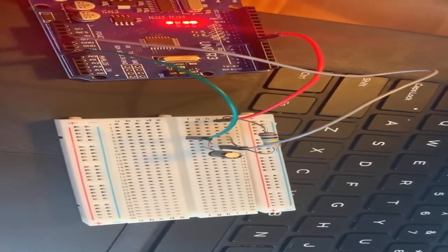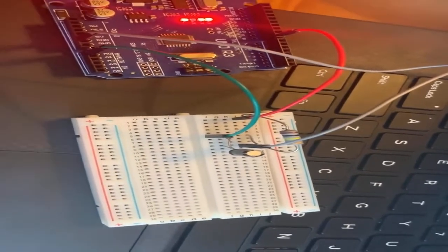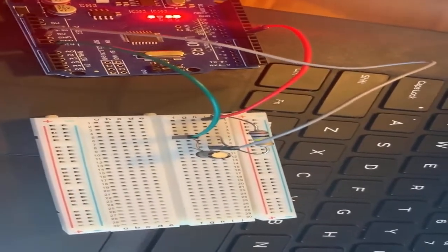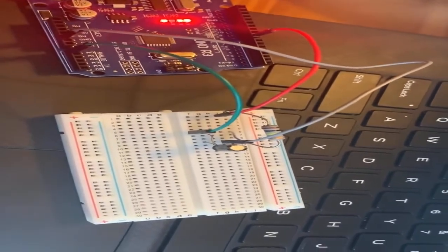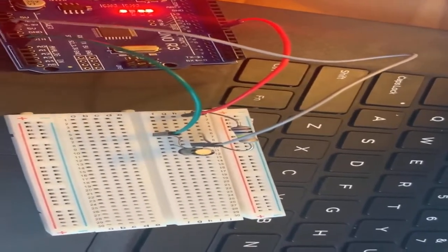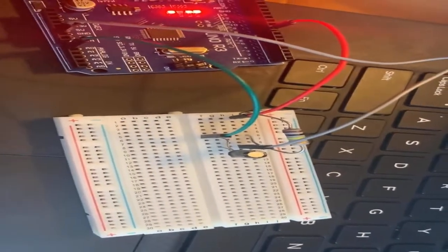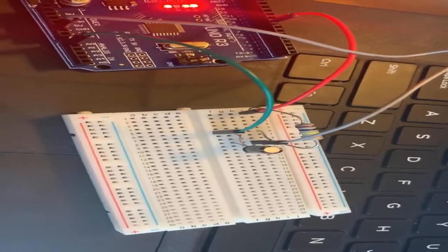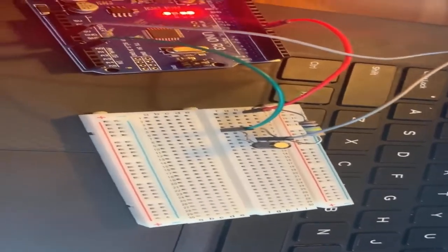So here is my circuit layout on my breadboard. Digital pin 8 sends in a specified voltage input from the Arduino IDE. This voltage is sent through the resistor, which is in turn passed to the capacitor. On the positive leg of the capacitor, we have a wire attached to analog input A0 to read the voltage that is being passed through the capacitor.